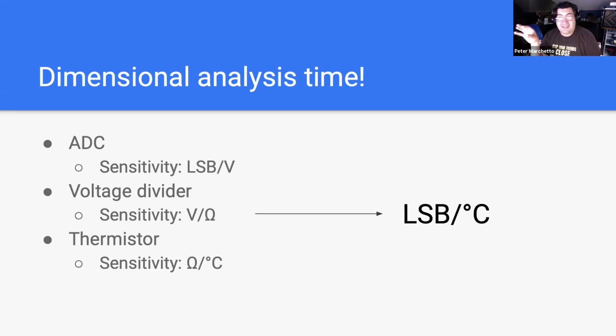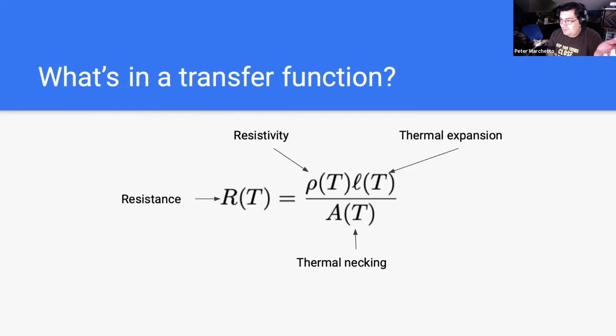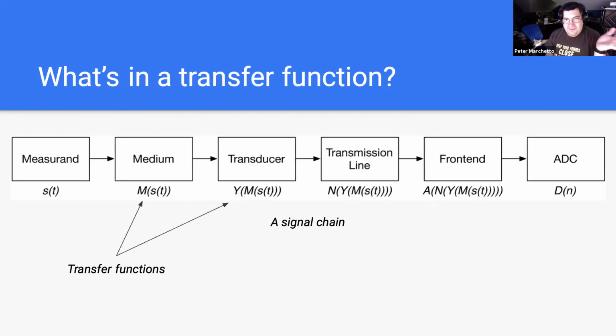This is a sensitivity that I can actually use because I get a number in from, in our case, a module board and the analog to digital converter on it. And then I can say, multiply that by this particular number and I get out a temperature. So my measured quantity has become, from a measurand, an actual number that sits inside of digital storage or memory somewhere that I can then analyze later.